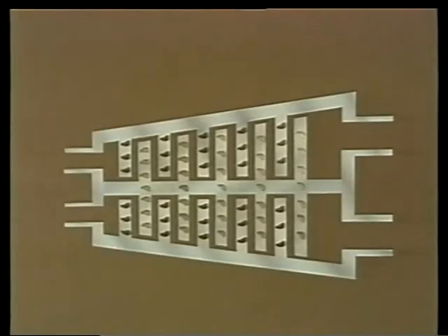Centrifugal compressors spin air out and around to the diffuser and the volute, where flow rate drops and pressure increases. Axial compressors have rotating blades that push the air down the length of the casing. Fixed, non-rotating blades are used to slow down the flow and raise the pressure. Let's see what an axial compressor looks like on the inside.